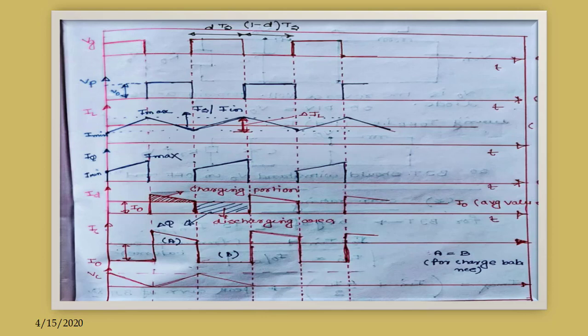So if we do that, the waveform will become in this fashion, and here this is the I naught. So we have subtracted. So now this line is the zero line. Are you getting my point? Because ID equals I naught plus IC, and this is my I naught. So what is my IC? IC is ID minus I naught. So I have subtracted. So now this line is the zero line, the T axis, and this is the nature of the capacitor current.